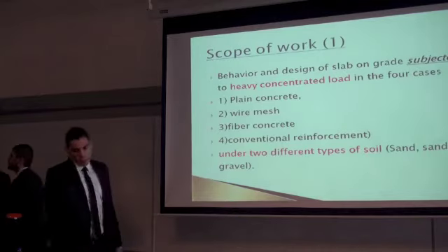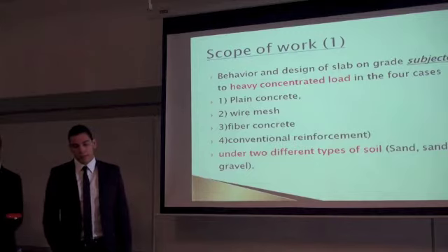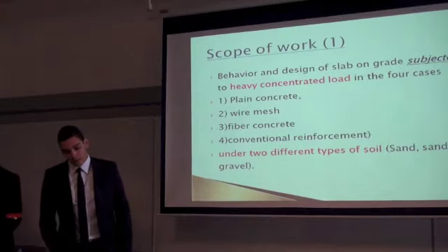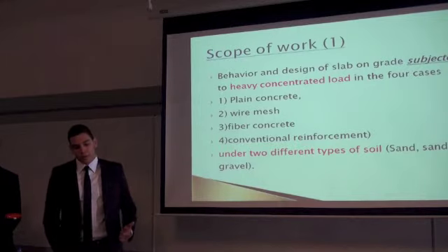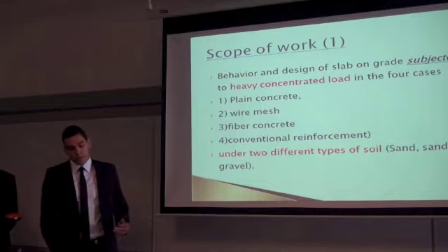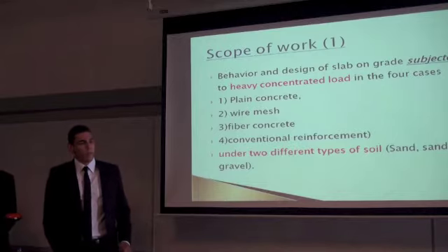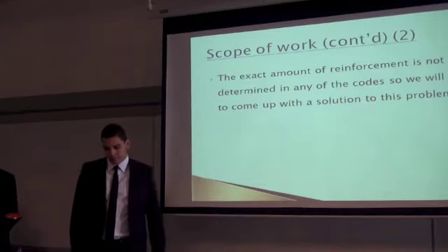We are going to tackle three issues in the scope of work. First, the behavior and design of slab on grade subjected to heavy concentrated load, in the four cases: plain concrete, wire mesh, fiber concrete, and conventional reinforcement, under two different types of soil. First, the sand, and second, the sand and gravel.